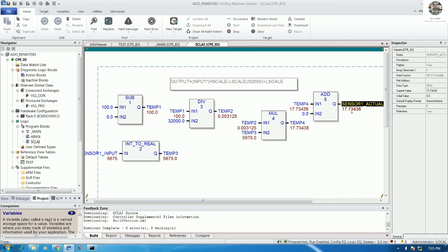So it's very easy. If we have a loop calibrator, we can use it to adjust a little bit, or we can use it like this to adjust step by step, from 4 to 20 milliamp. Yes, like this. So the next step, we need to show this value on the HMI, right? So let's go configure the project for the HMI. Yes, let's go.